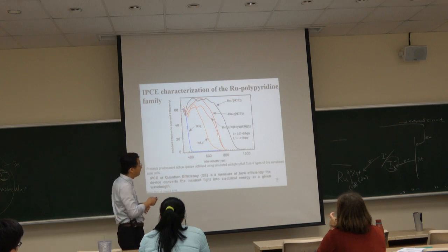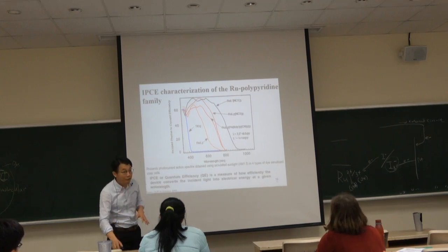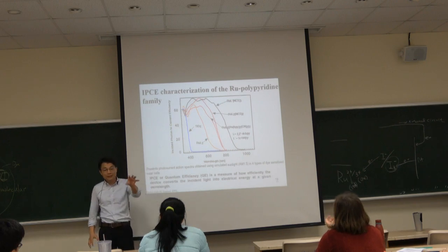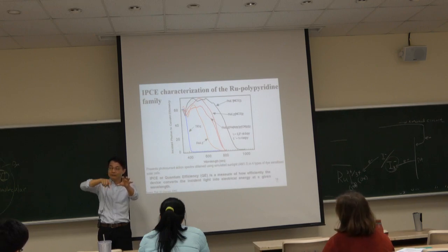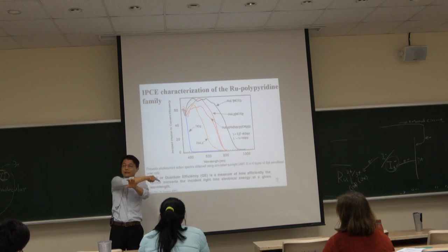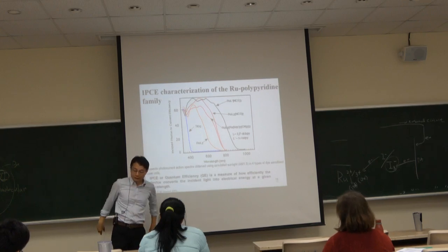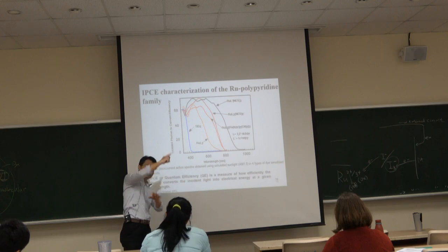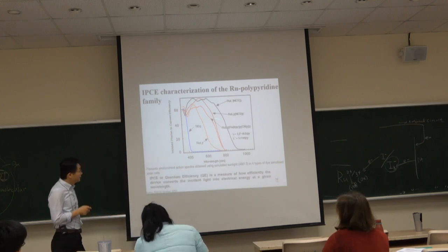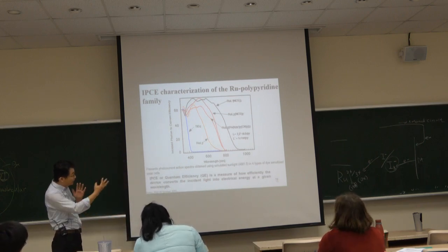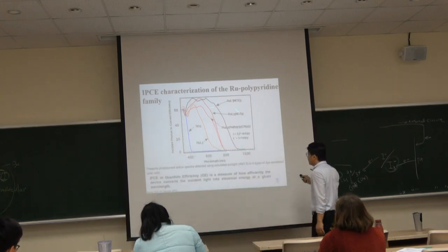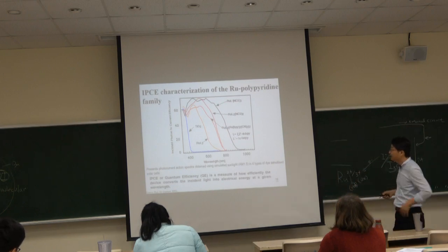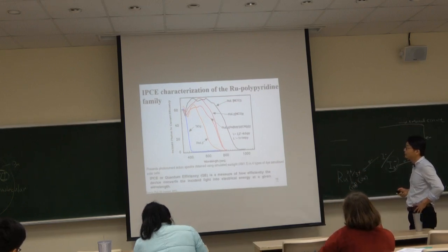Okay, so I would say they are just like a partnership. TiO2 is right here, dye is right here. The functionality of the dye is to absorb the light and promote the electron to TiO2. TiO2 transfers to the ITO, and then to the external circuit. Therefore, we have to design the dye for longer wavelengths as much as possible, and then we can cover the whole spectrum.